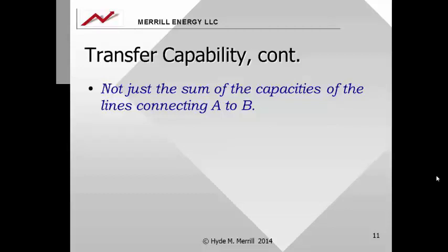Transfer capabilities are affected by the ability of each system to generate power and to absorb power. The transfer capabilities are affected by transmission lines that may appear to be remote to the interface between two systems. This is because the entire system is involved in every transfer of electricity. And between ECAR and MAC, the transfer capability may be limited by the overloading of a line down in Virginia or out in Tennessee or someplace else.